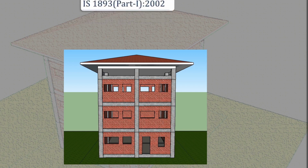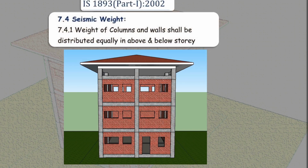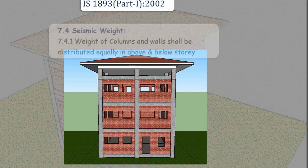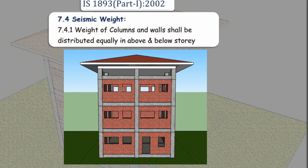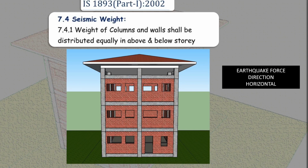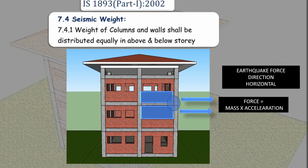Now coming to the earthquake load. If we look into the earthquake loading, as per IS 1893-2002, clause 7.4.1, the weight of the columns and the walls shall be distributed equally to the story above and below. What it means is that when the earthquake happens in the horizontal direction, if we consider this point, the load contribution will be from this portion, which means that half of the mass of the wall above that point and half of the mass of the wall below that point will be contributing to the horizontal force at that point.